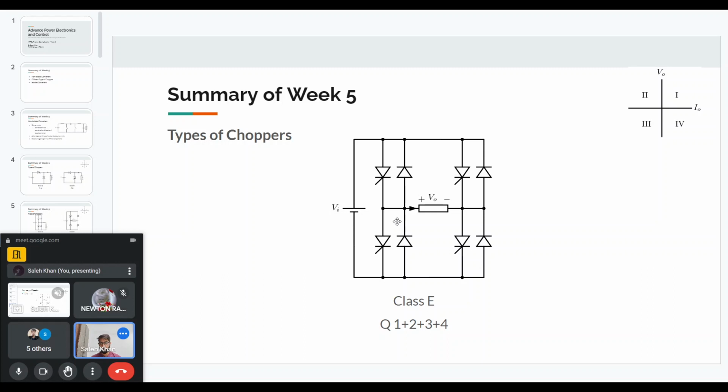And finally, we talked about isolated converters and the reason why we use them. We basically use them for safety reasons, to prevent noise, and to get an output voltage that is not at the same ground as the input voltage. Finally, for very large transformation of voltage, from very high voltage to low voltage, or very low voltage to a higher voltage, we can use isolated converters.